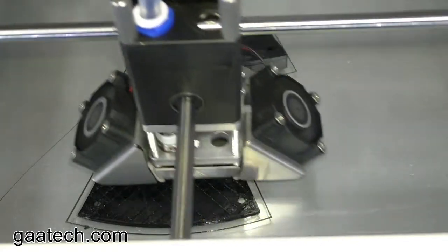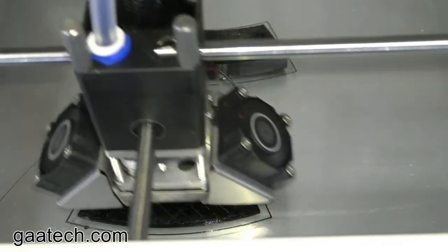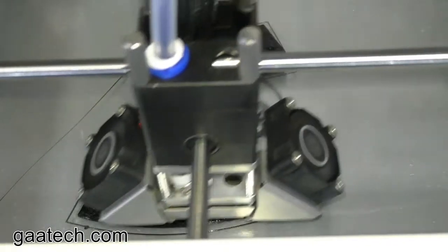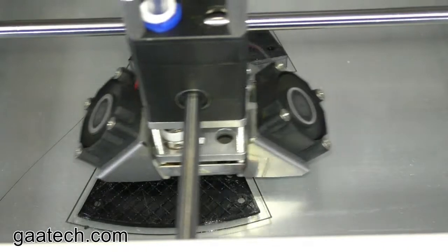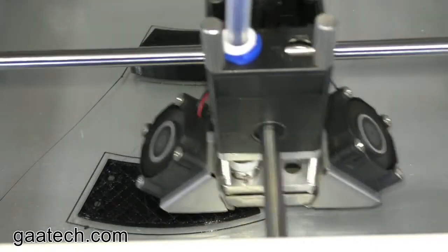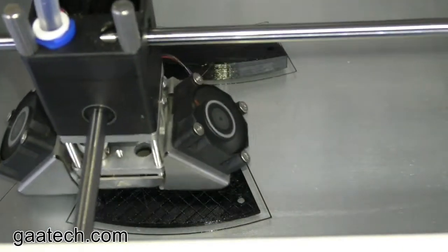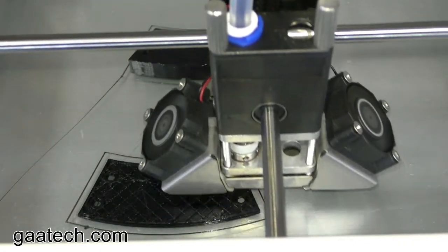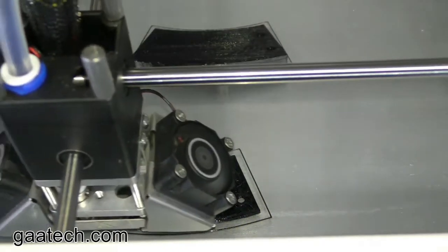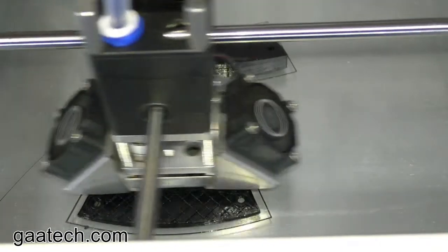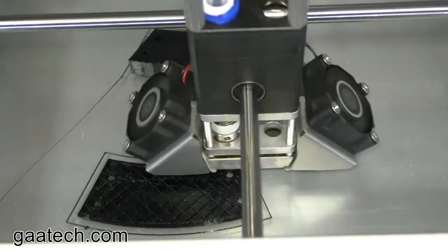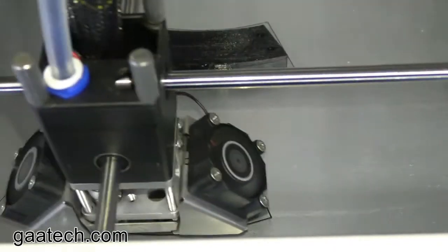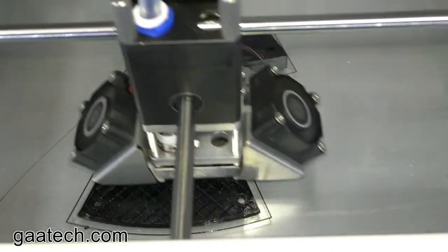Now this infill is 20%. So you can see the hatch pattern is actually quite visible. I would say, looking at it, it's maybe 4 mil in between lines. Obviously the more infill you request in your print, the denser the infill becomes and the smaller the diamonds or the square patterns become, which affects the time that the printer takes to print.